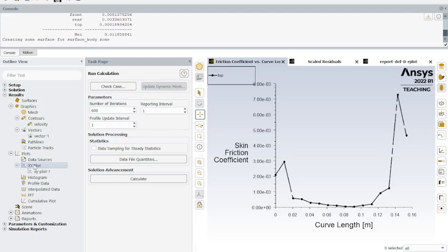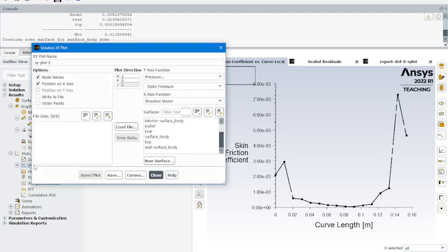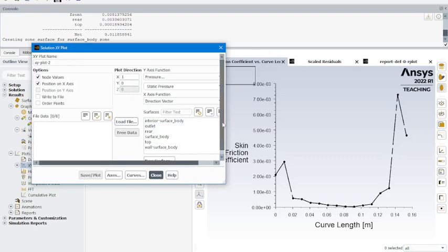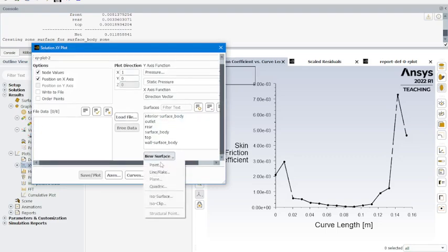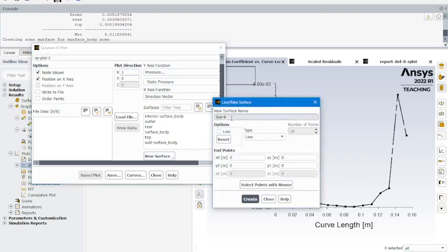We're going to do that for our next one, which is looking at the boundary layer velocity profile. Now we already saw with the vectors, but in order to do this, we're going to do it at the midway point of our flat plate. And to make these surfaces easier, we're going to put x equals 0 because we centered our flat plate. And y equals 0.006. And that's because I've calculated the boundary layer. And I've done this simulation before, and 0.006, even though it's much farther out than the boundary layer that you would calculate, it seems to be about where the velocity equals the free stream velocity.